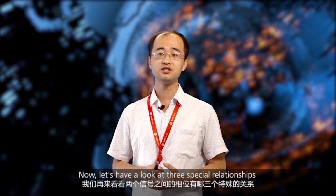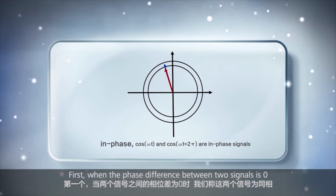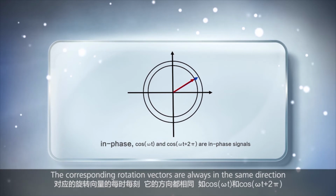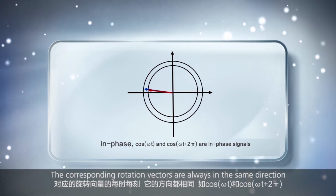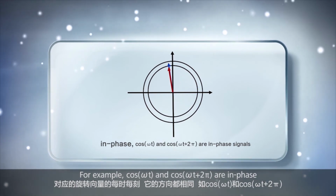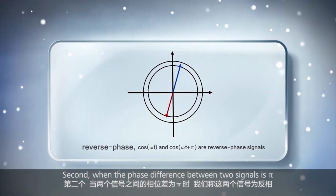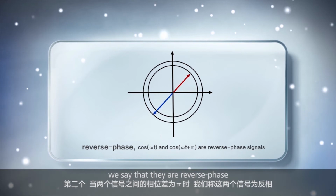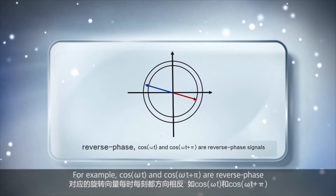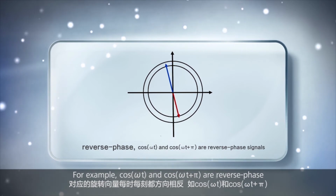Now let's have a look at three special relationships between the phases of two signals. First, when the phase difference between two signals is 0, we say that they are in phase. The corresponding rotation vectors are always in the same direction. For example, cos ωt and cos(ωt + 2π) are in phase. Second, when the phase difference between two signals is π, we say that they are reverse phase and rotation vectors of each signal are in opposite directions. For example, cos ωt and cos(ωt + π) are reverse phase.